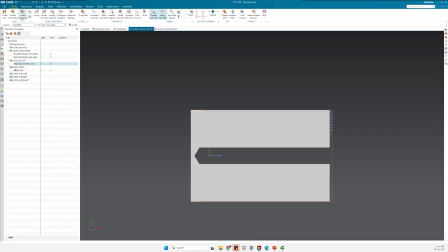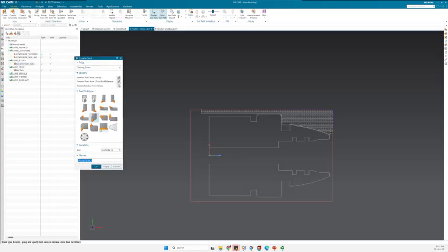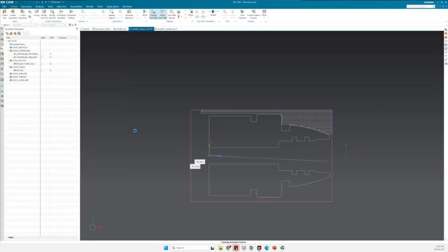So for the operation of grooving, we need to first create the tool, maybe. We'll first create the tool. It's the outside groove. It's actually this one, outside groove L. I'm going to define it in, let's say, station 5. If I want to put any size, I can, since I might actually use two different groove tools or something like that, but now let's use only one.